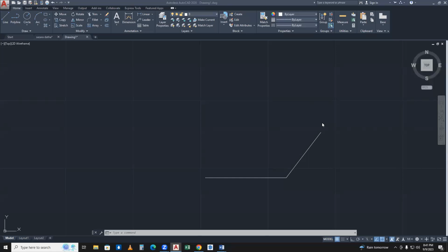Okay, we will find now. We'll see. Okay, so we are done with the 2.12 line and we need another 2.83 line in 90 degrees, right? So we are going to draw another line. What is the angle we need? 90 degree. And what is the distance? 2.83 meters. So see, now when you have the F3 snap mode on, it is showing us the perpendicular.